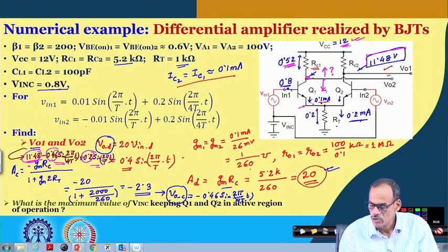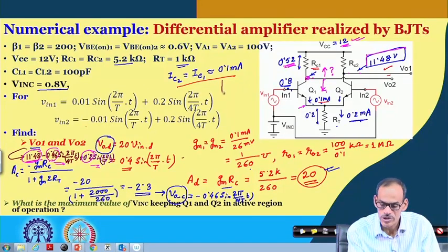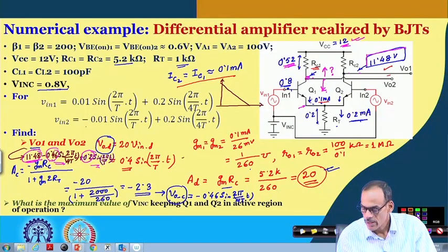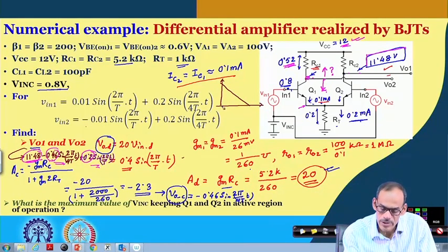In fact, you may recall positioning the operating point with respect to the load line. So, suppose this is the load line defined by the corresponding RC that we have discussed for the common emitter amplifier, and if the circuit is in good condition, then the pull down element should be such that the operating point should be in the middle of this range.